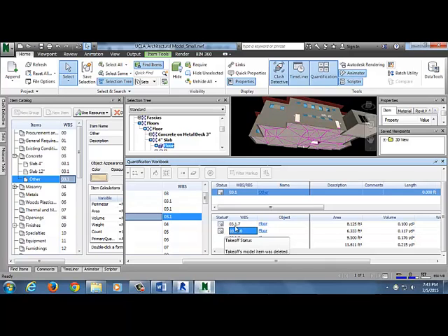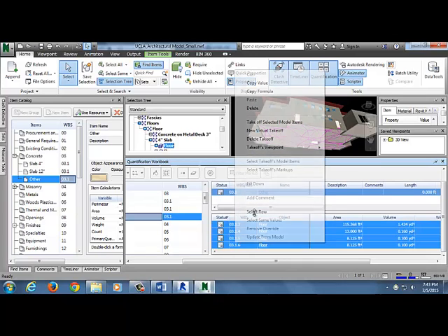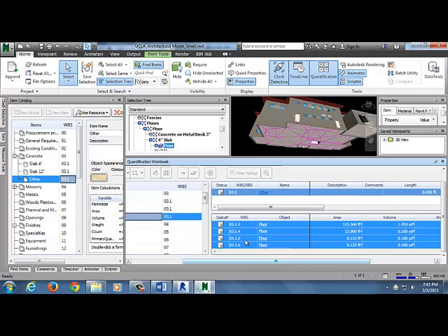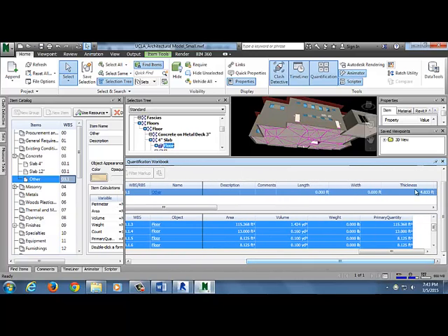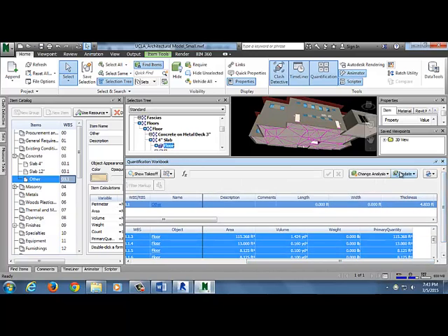So item was deleted, item was deleted. So looks like there were a few floor pieces that were just straight up deleted. So I right click, I have to select the entire row, and instead of right clicking I could also say up here update. I can't update because they're deleted, right? So delete the takeoff.